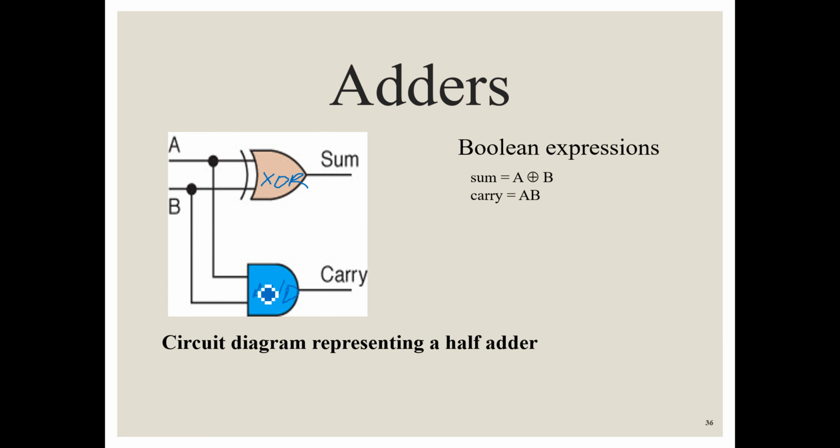This is the adder circuit. A half adder is a two-input addition circuit. Why? Because if we are talking about a half adder, then definitely there is another kind of adder called a full adder. A full adder will be a three-input addition circuit. Now what is the functionality of this adder? The functionality of the XOR gate will be the sum, whatever functionality of XOR comes out, that will be the sum, and the functionality of the AND gate will be called the carry, that becomes AB.